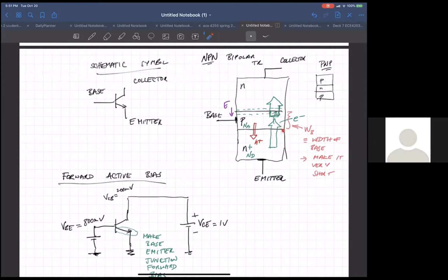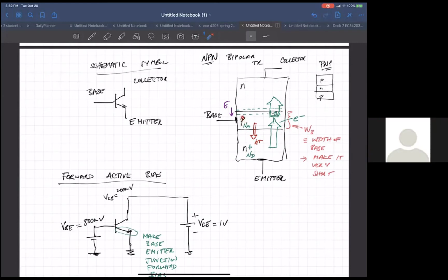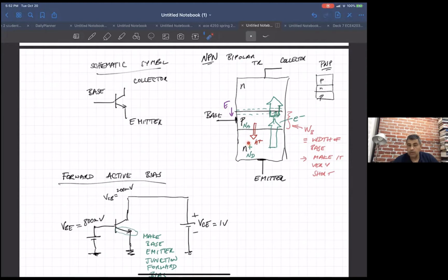Oh, okay. So, yeah. I apologize if I screwed that up, but basically in this op mode, there's two junctions, right? Because we have N, P, N. So there's a base emitter junction and a base collector junction. The base emitter junction, you'd like it to be forward biased. So you want to make this P more positive in voltage than the N by more than a VD on. So that's why I put this 800 millivolts there.